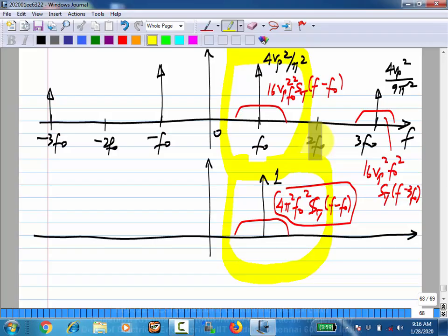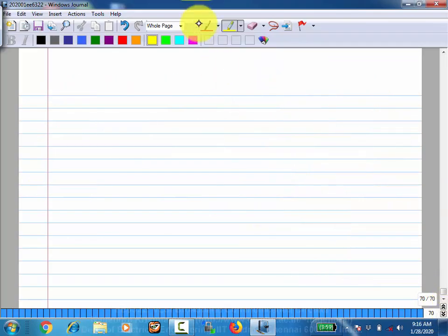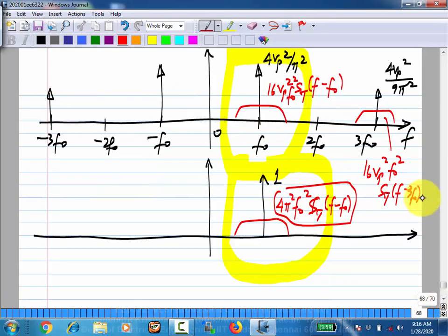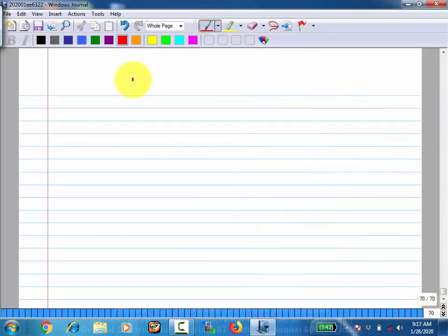Is this fine? So if you do the calculation, you will get exactly the same thing even around this. But keep in mind here the frequency is 3f naught. So the phase of this signal would be 6 pi f naught times tau, right? The phase jitter corresponding to this frequency. So you will always get basically an impulse, and if you normalize it to that impulse, what you get will be the phase spectrum. Okay? Spectral density of phase jitter.